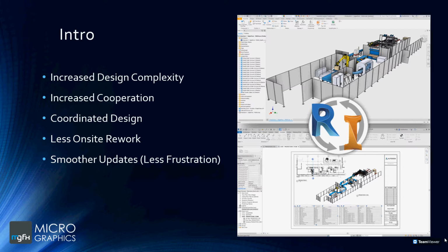So we'll be taking a Revit model, bringing it in. That gives us our floor space that we have to work with. We can then design and place in the equipment relative to that workspace. This equipment that's been placed in will then be exported from Inventor as a Revit file, a native Revit file.